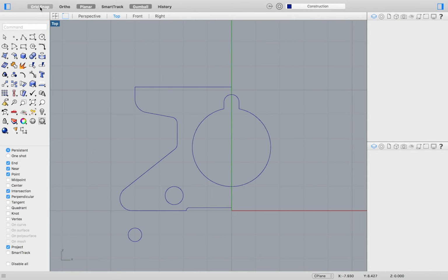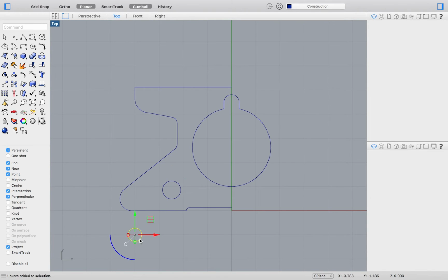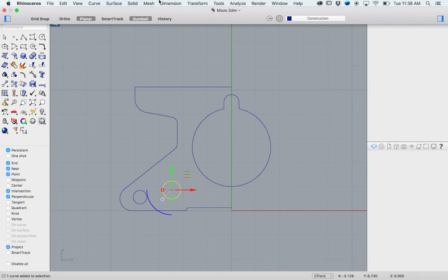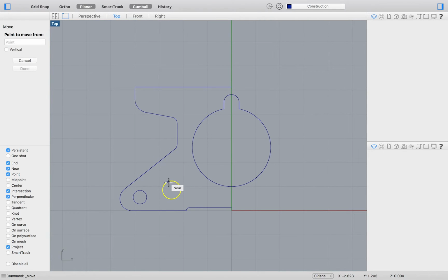For learning how to move, I will open the move.3dm file. You can turn off ortho and grid snap to be able to move your object freely. We can gumball the circle or just simply click and drag it. However, you are probably more interested in how to move the circle to a more exact location. Now, remember our past lesson on absolute and relative coordinates. Those same methods of point entry will apply to moving your object.